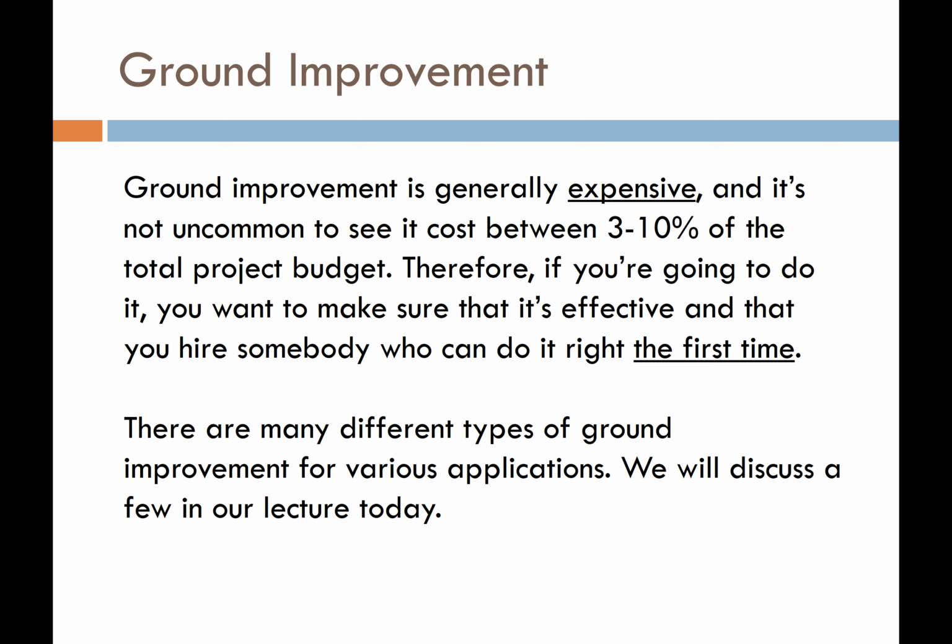So a couple of things that you need to understand about ground improvement. Some students may and have asked me the question, well, why don't we just do ground improvement for every site? Well, here's the problem. It's because it's really, really expensive. Ground improvement in general, based on my personal experience in consulting, generally increases the total cost of the project by 3 to 10%.